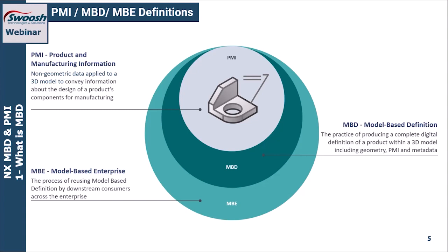The next circle down, which is model-based definition. Model-based definition is the practice of producing a complete digital definition of your product within the 3D modeling application, and that includes the geometry, the PMI or product and manufacturing information, and the metadata with that digital file. And the largest circle here we're looking at is going to be the model-based enterprise. The model-based enterprise is the process of reusing model-based definition by downstream consumers across the enterprise.